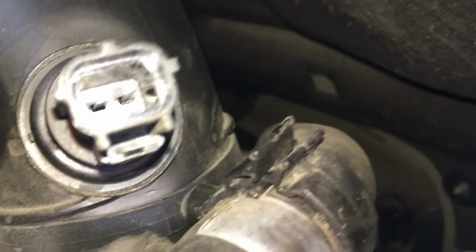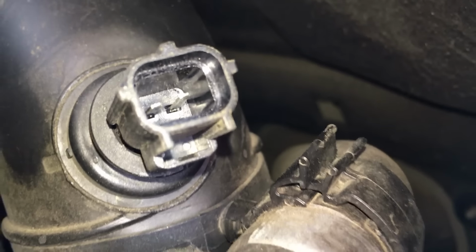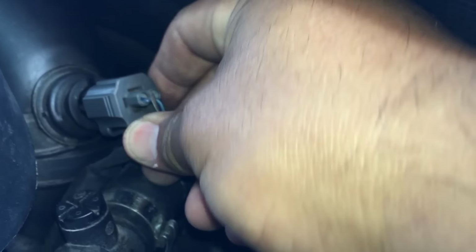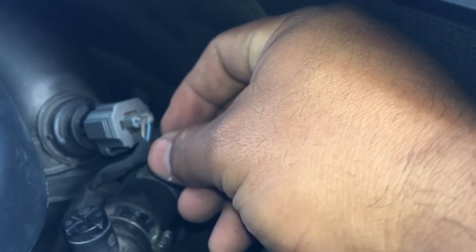As you can see over here, it is still plugged in. I'm going to unplug it. Look inside the connector. The connector itself looks okay. The pins inside the sensor, pins look nice and straight. So this air intake temperature sensor looks to be okay. Let's go ahead and grab the graphing meter and let's back probe these pins here.